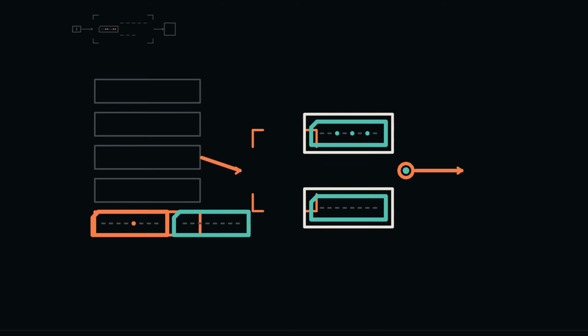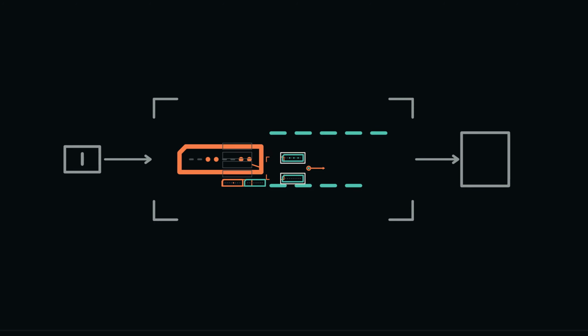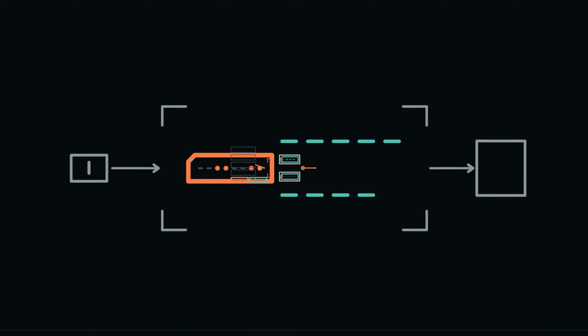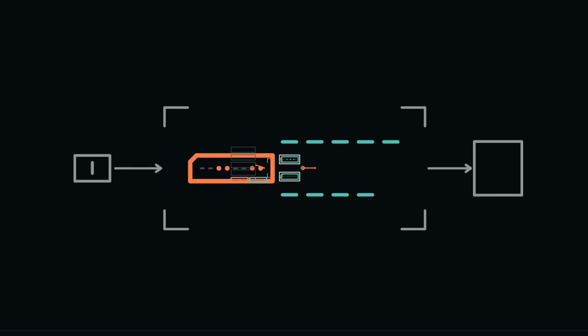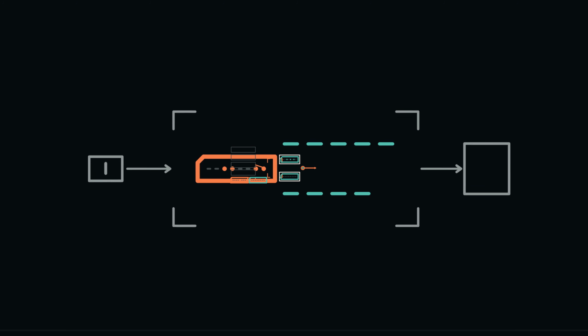You have now run a machine state the film did not reveal in advance. The transferable method is simple to state and demanding to apply. Identify the current stored state, fetch the exact 2 instruction bytes, apply only that instruction's semantics, record the committed result in flags, then determine the next program counter. Never skip from a mnemonic to a hoped-for outcome.